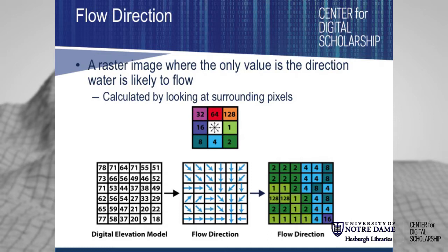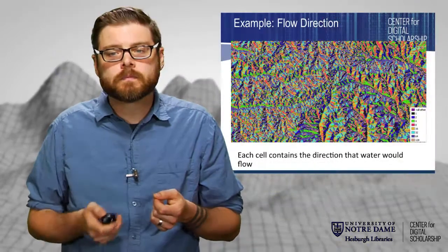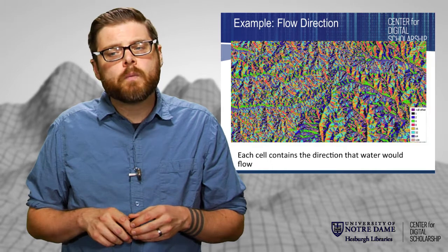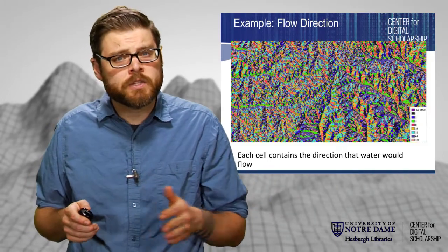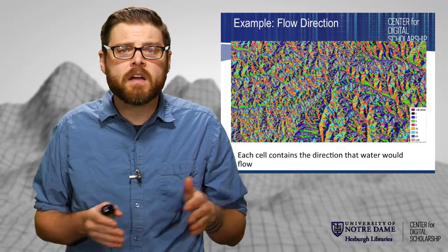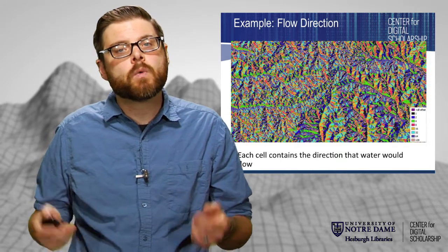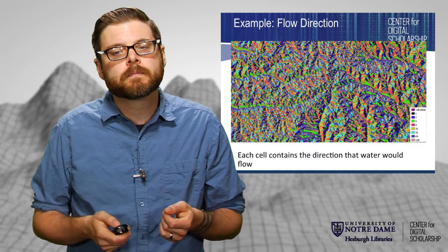If we're not able to determine which direction water is likely to flow, we can record that in that pixel value. So this is what one of these might look like if there is a lot of this ambiguity. We have essentially an 8-bit image, with values 0 to 255, or 1 to 256. So each cell contains the direction that water is likely to flow from it.